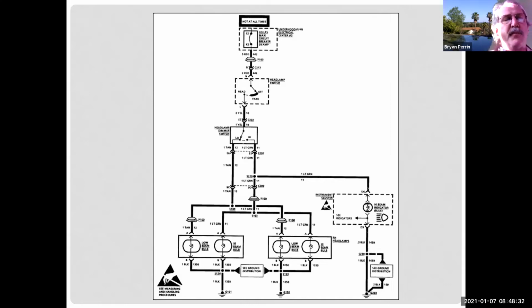And it's two different things. Mitchell does a good job of, let me hold your hand and we'll walk through these steps to try to solve this code. But they won't tell you what the computer saw to set the code. ALLDATA tends to say, here's what the computer saw, here's what made it unhappy, here's the schematic, go figure it out. So I like that because I want to know what made the computer unhappy so I can fix it. What I hate is going through a diagnostic chart where I'm on step 3 with a meter wanting to know if it's above or below 11 volts, and I have no idea why I'm doing it or what I'm trying to figure out. Or I get to the bottom and it says replace with known good unit.